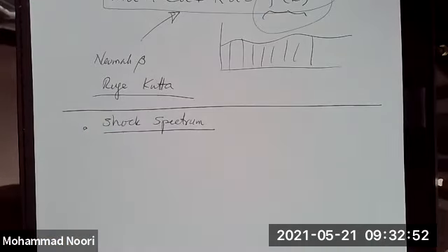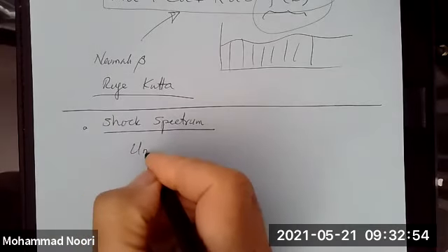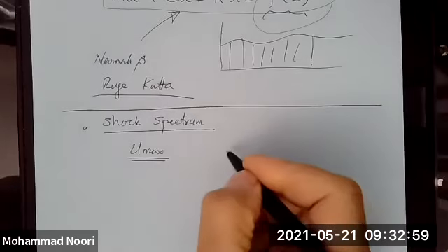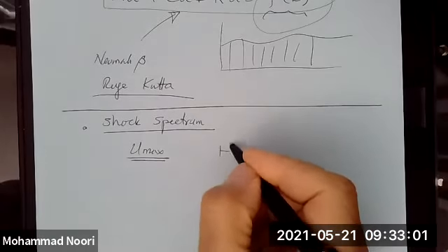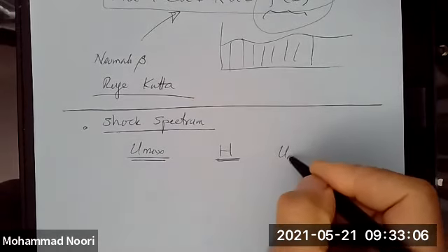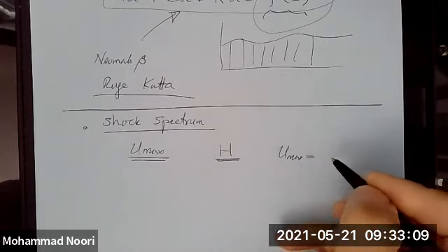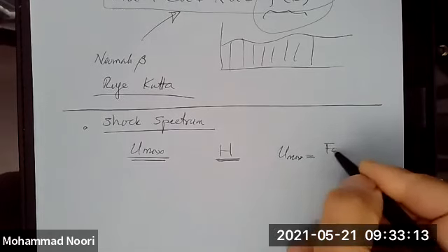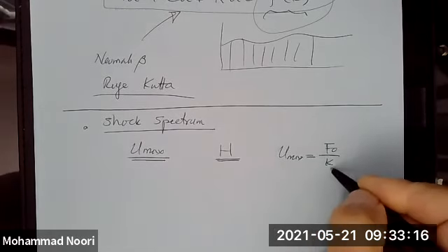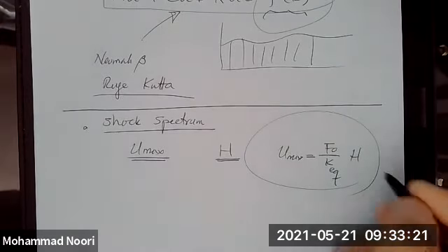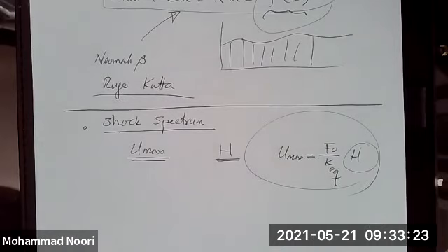In fact, somebody last time asked me a very good question, and that is, if you have a sinusoidal loading or harmonic loading, you can easily find the maximum response by having the frequency response function, which you can obtain, right? So the maximum response in any dynamic system subjected to harmonic loading, you know by now, can be found from this relationship where h was the frequency response function.